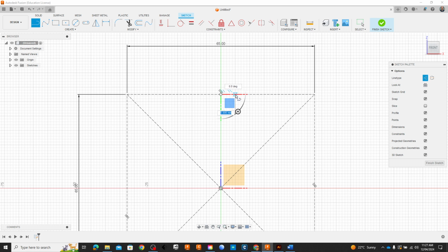Any thinner than that, you can push it a little bit perhaps, but if you're making a stem that's only a couple of millimeters wide, it's going to break as soon as you try to test it, okay? So my recommendation is make it 5 millimeters in half profile, then when it's revolved, it'll be 10 millimeters wide. Make it shorter, but I would maintain the 5/10 millimeter dimension.